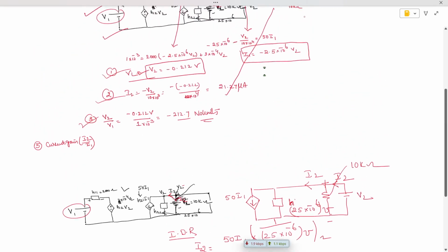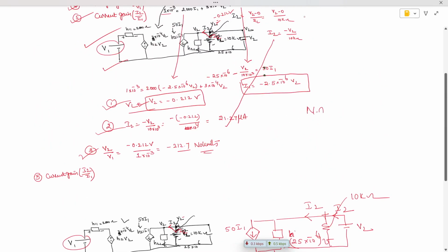So we have to understand nodal analysis in a very simple way. For example, you have a voltage V1, a resistance R1 like this, and a voltage source V2. So how to write the current in this branch? I1 is equal to, this is positive, the current leaving terminal: V1 minus 0 divided by R1. This is the current I1 flowing from top to bottom. But if you want to write the current I2, I2 is nothing but minus I1.